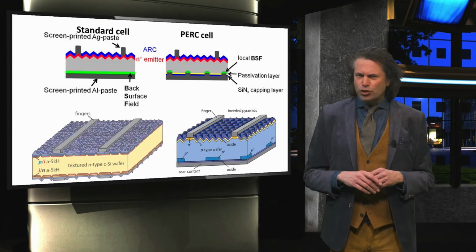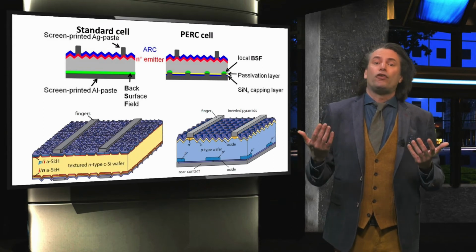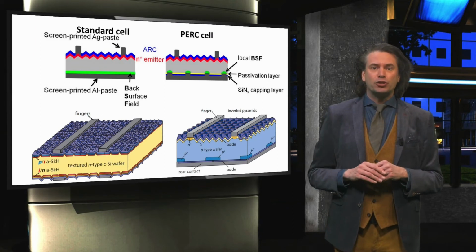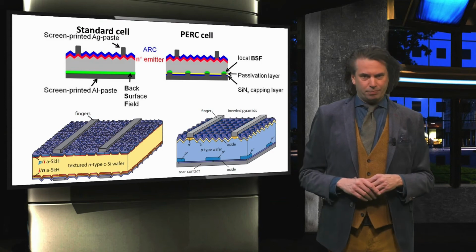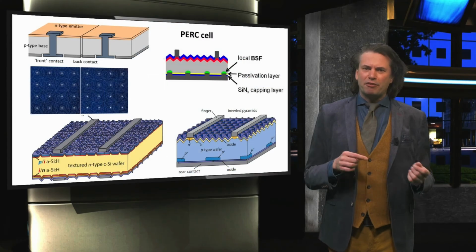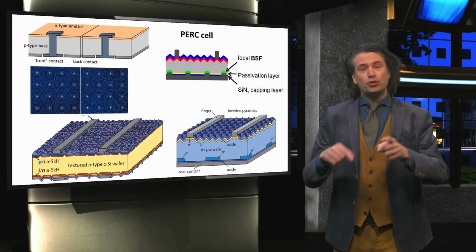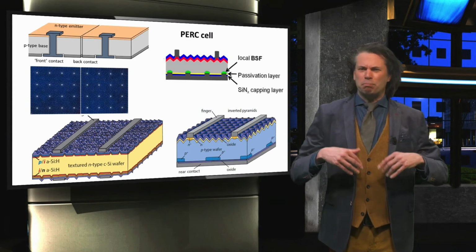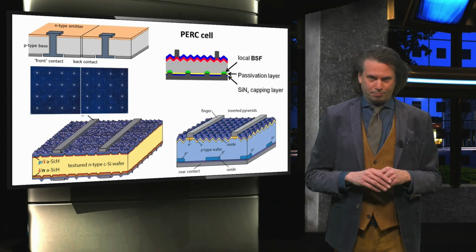The silicon heterojunction solar cell optimizes the open circuit voltage as the amorphous silicon passivation layers form a heterojunction with the crystalline silicon wafer. The metal wrap-through technology can be implemented for module optimization by transporting carriers collected at the front of the cell to the back. Using this design, the individual cells can be placed much closer to each other.